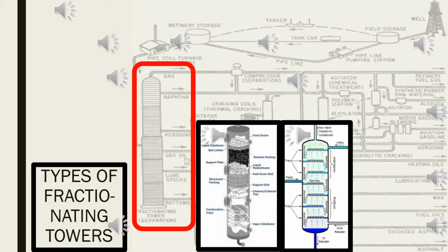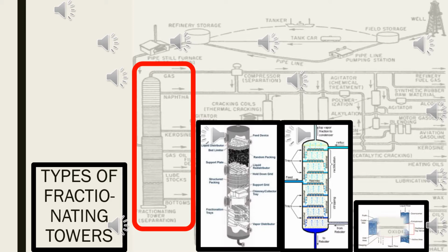Secondly, you can also choose a tray distillation column for the crude oil fractionation that you have to do. Each tray essentially acts as a mini column, therefore accomplishing a fraction of the separation task. From this, you can deduce that the more trays you have, the better the degree of separation. This also applies to the packed column, but here you consider the theoretical number of plates.